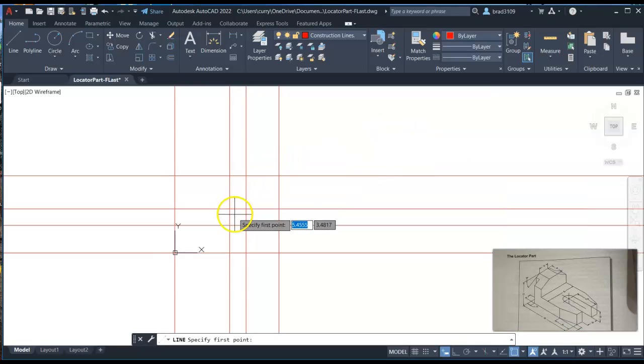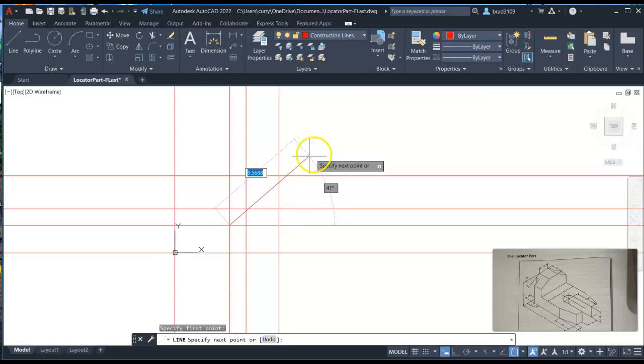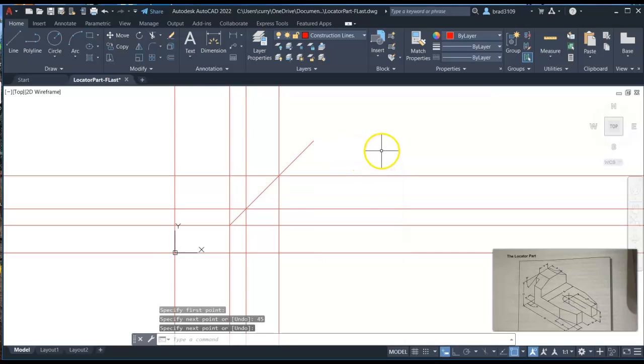So now I'm going to go back here. This is my point where I'm going to start the 9th line, and I'm going to move this up and over. Now remember, you will see it is auto default. You've got that snap point there, but I mentioned don't use the snap point. Draw this up and over. Whatever the line is, just tab over and make sure that you physically enter this at 45 degrees. So right click and enter to get out of the line.